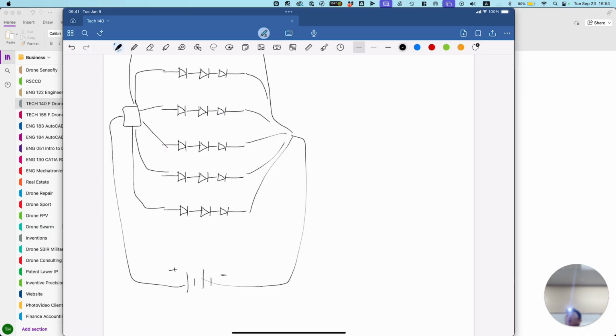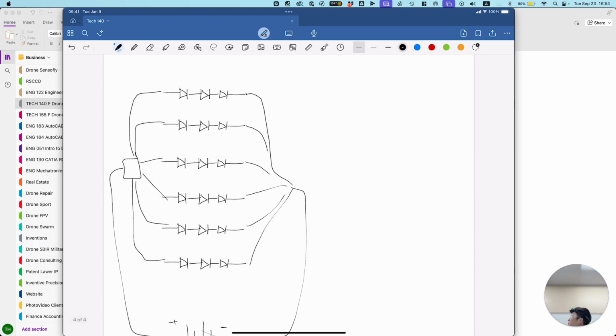That's why earlier I was running down one side and everything beeped, but the other side only beeped in groups of 3. So what you see, here's our series within each grouping, but then they're all parallel to each other. So that's what's happening in this thing. And this board right here is just distributing the timing of when each of these turn on one after another.